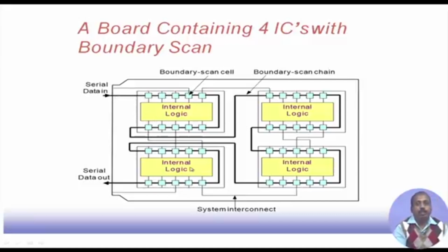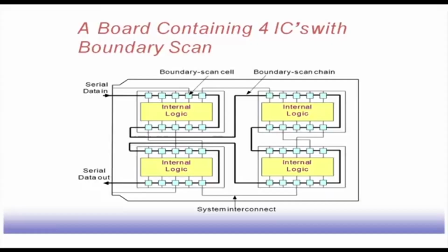Apparently it appears that it is very costly to reach individual chips, but still it is much better than going by the logic of the circuit. In most cases the logic of the circuit is not known, because we are buying the chip from the vendor. So, we do not know the internal logic, or what value should be given at a particular point at a chip level.